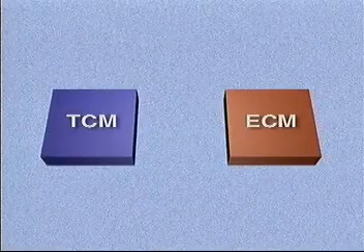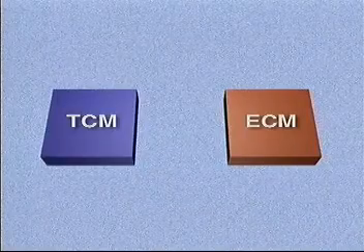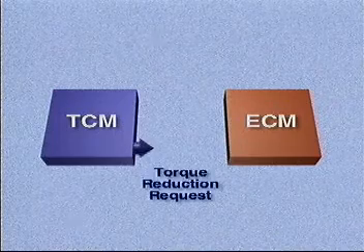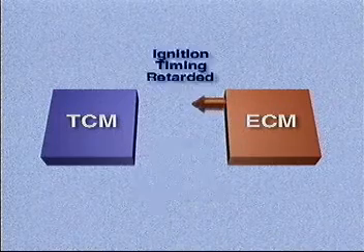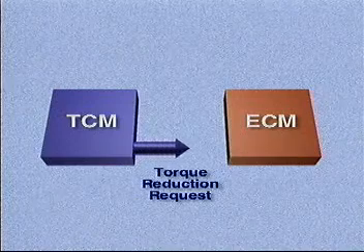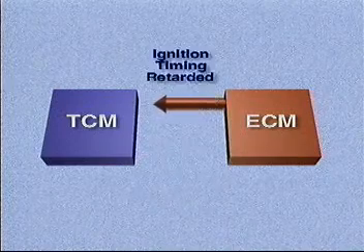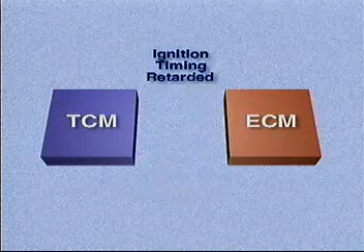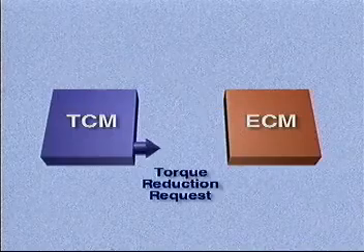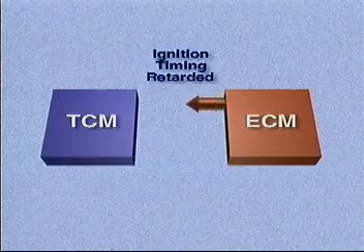The engine and transmission total control system, which is used on other Mitsubishi models, improves the shift quality on 1997 Mirage models with automatic transaxles. This system reduces engine torque during transaxle shifts to ensure a smooth and positive shift.